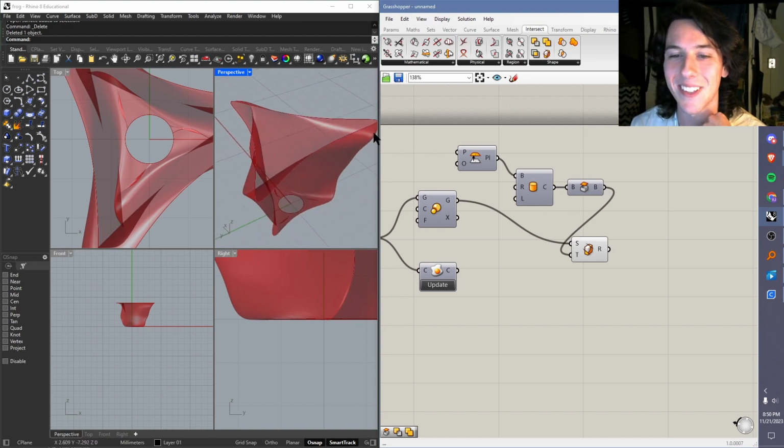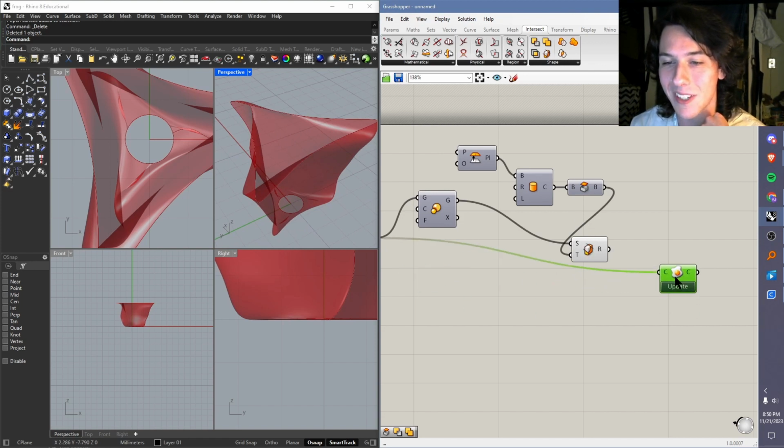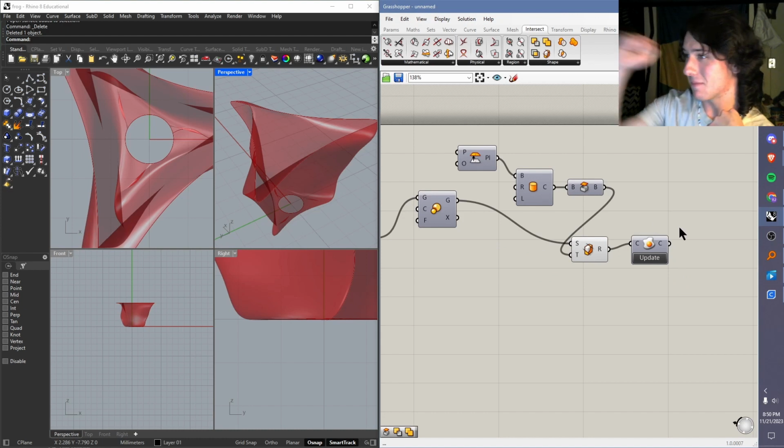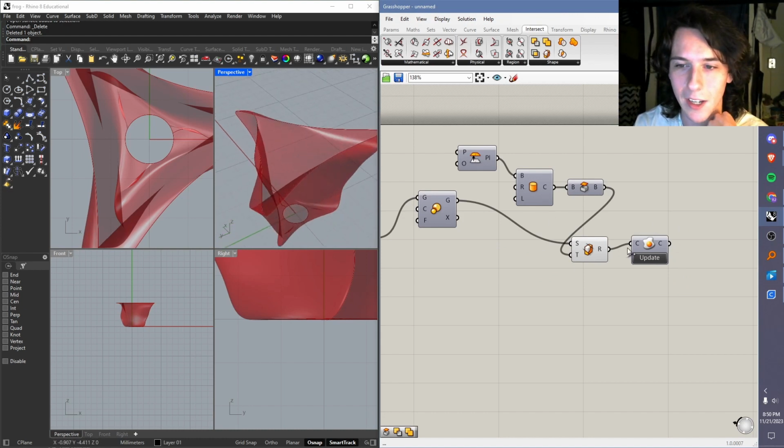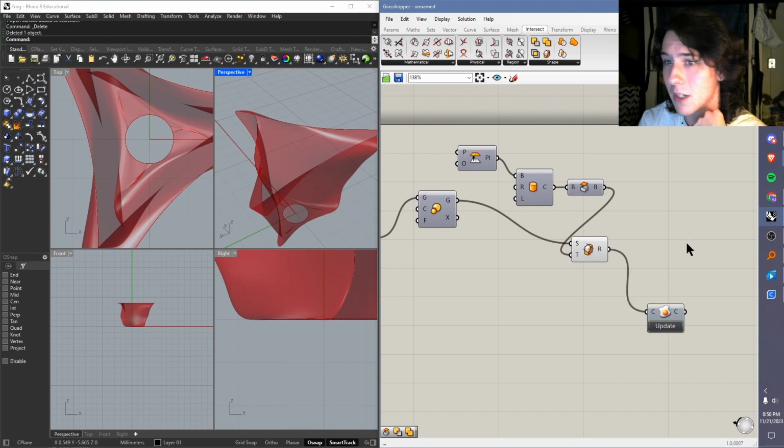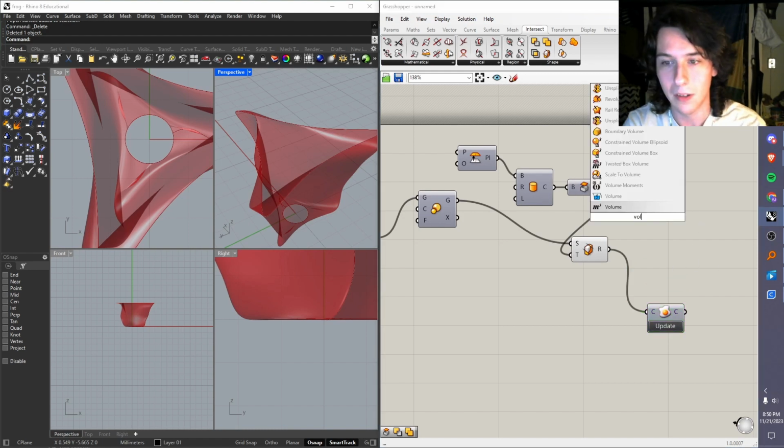Lampshades don't need thickness. Now, suppose you wanted thickness on this, which I'd be wagging my fist at you. I'm going to be real with you. My recommendation is to do it on the Rhino side. Adding thickness in Grasshopper is really difficult. Maybe I'll add a hypercut here of me trying to add thickness to this, and I think it'll be really funny to do that. Okay.